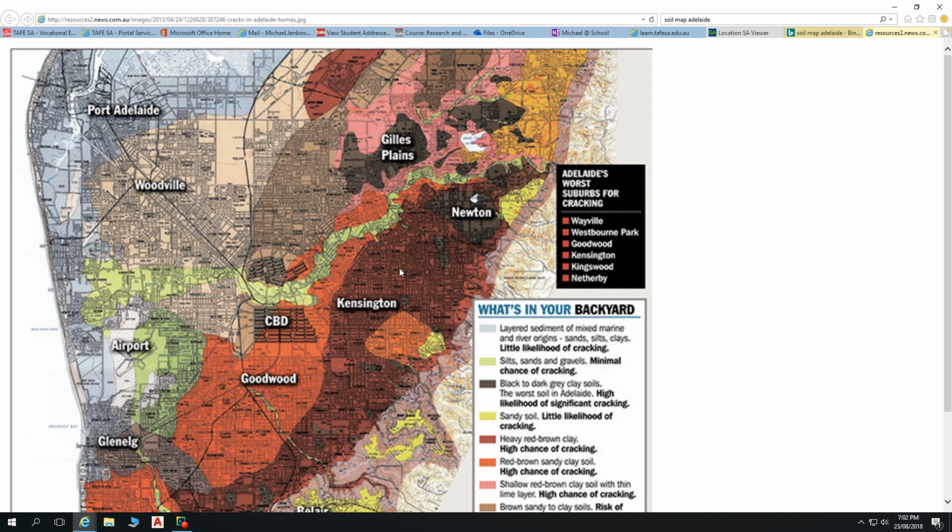The buildings in Parkside, Unley, etc., were built on strip footings. You've got solid masonry walls, probably about 200 mil thick, on bluestone slab footings. That can't handle that sort of reactive soil. So there's movement and cracking, and you've got walls wandering away from buildings, and tie rods through buildings to hold them all together. Whereas that footing technology has changed significantly.